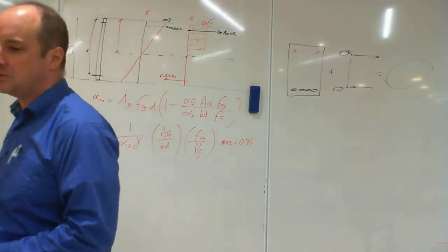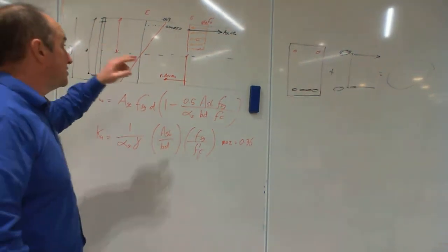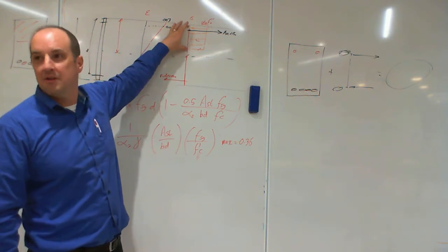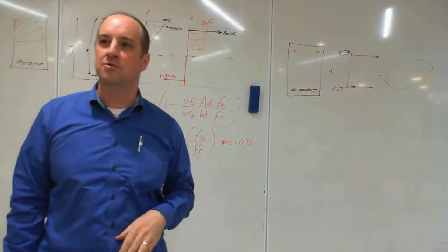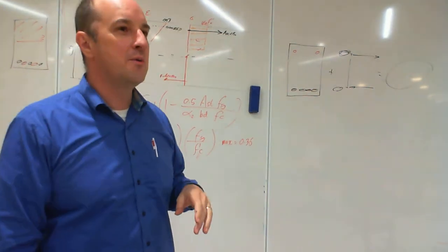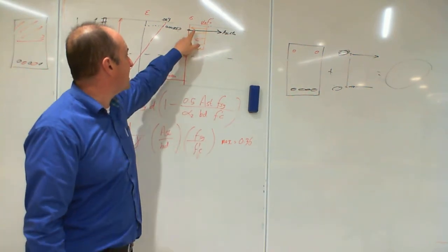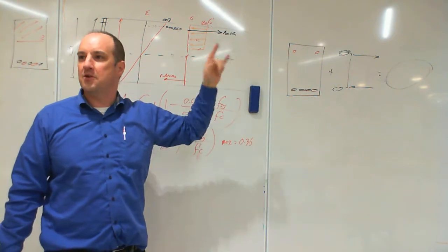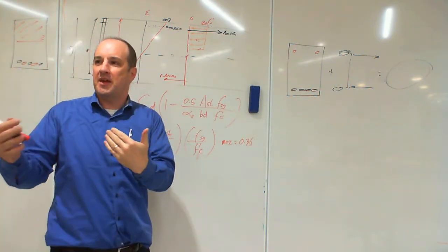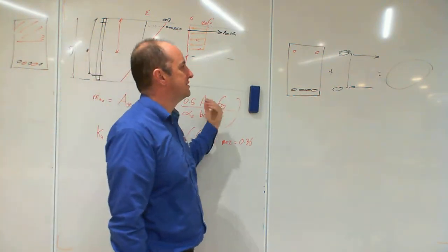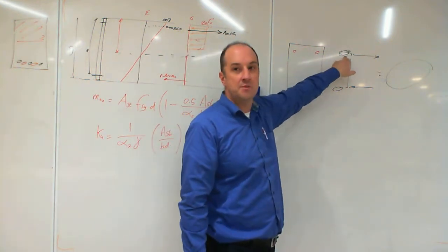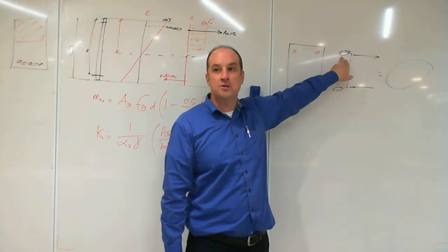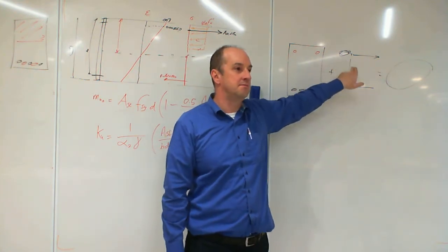The difficult way to deal with that would be to say, all right, what's the new area of this concrete? What's the new centroid? What's the new distance? And that just sounds like torture, so we're not going to do that. The way we do it is to say, all right, let's pretend that if that steel bar was concrete, let's pretend the bar's not there and pretend it's just concrete, and let's deduct that same amount of stress from here. So if that was 32 MPa concrete, we take 32 megapascals away from our force there.